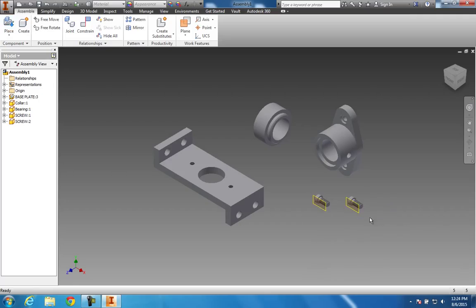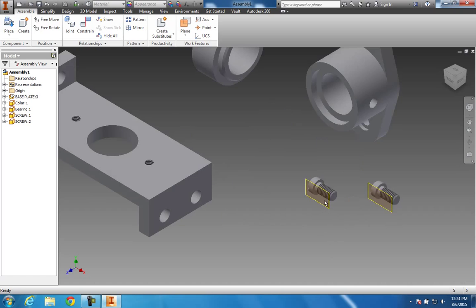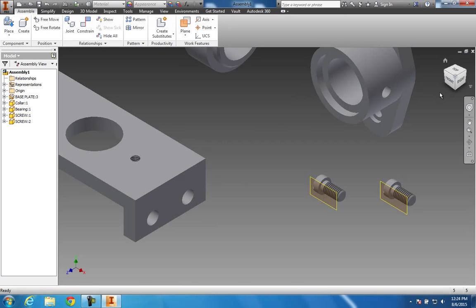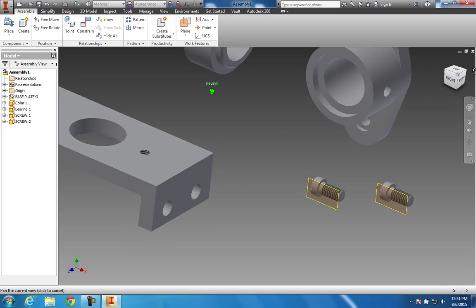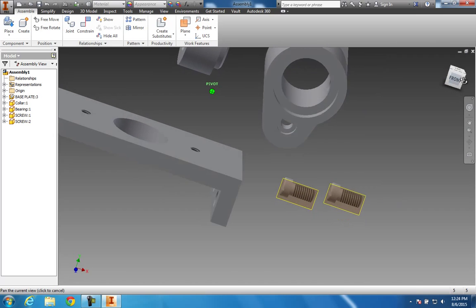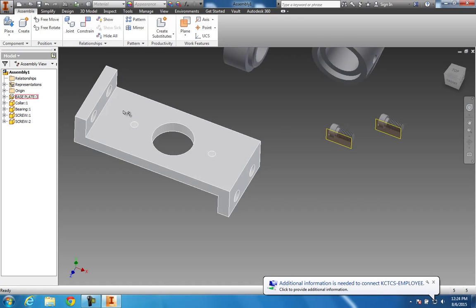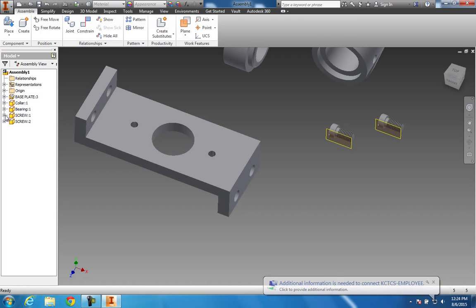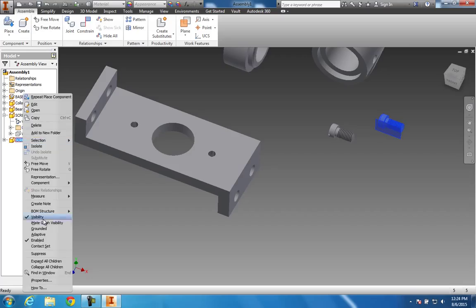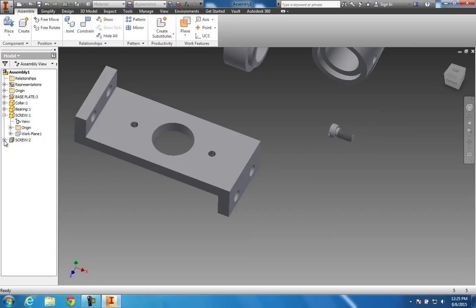Right click, OK. And you can see the visibility is on that plane where we had to put that slot for the screwdriver. I used that work plane to build that on. So if you want to turn that off, all you have to do is come over here and find it. See, when I highlight over top of them, it'll find it. And come down here to work plane, right click, and just go to visibility and turn it off. One thing about a work plane, when you print, if you got a work plane turned on, it won't print.